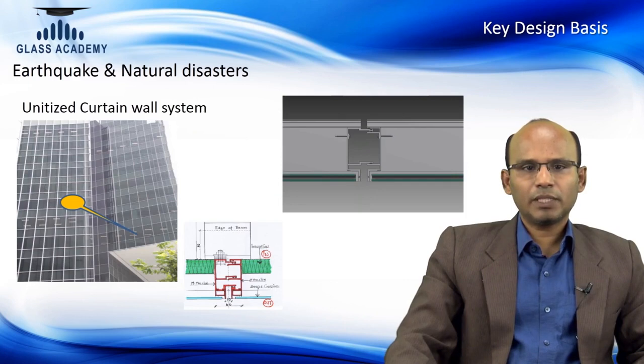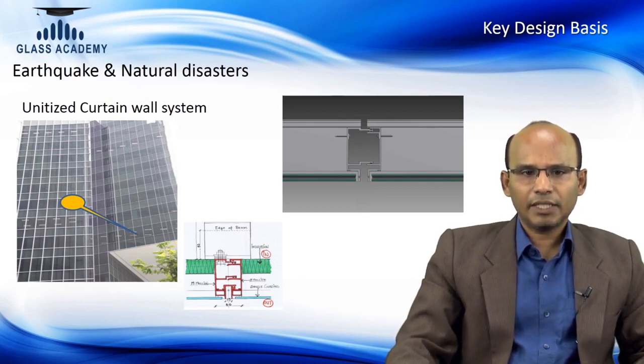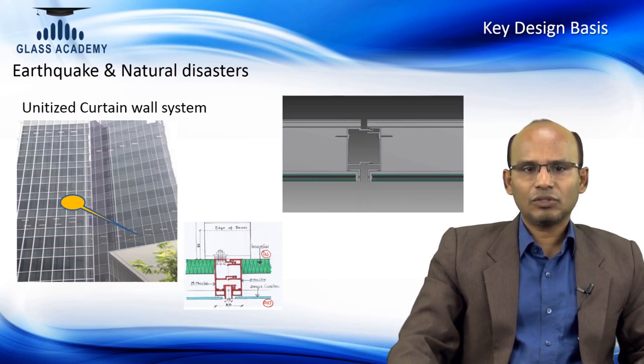Continuing with the building movement, for the facade system you can see a typical section detail, the glass here, and it has a framing arrangement, and there is a bracket which is holding these panels. So this is primarily, if you take a curtain wall glazing system for a commercial building, generally this system is adopted. You can see it's a glass building, the glass is used at this level. When you see from the floor level it is different. At the face of the beam it has a darker band here, which is using a different glass combination, but the system is